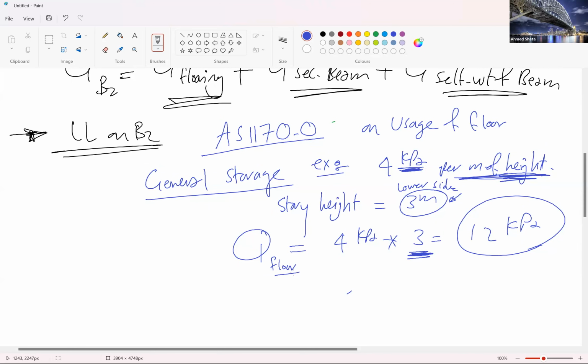The lower side is not given, so you used trigonometry to subtract and get the smaller height, right? Yeah, that's what I did because it's not given. You're given the highest side of the eaves height, but not the other side. Yeah, you need to subtract the projection of the difference and then get the smaller side.